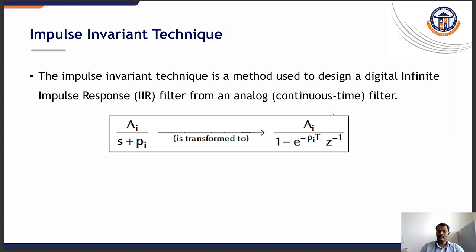While the bilinear transformation solves the aliasing problem, it also introduces a different issue known as frequency warping. The relation between the analog frequency and digital frequency is actually nonlinear, which means that frequencies in the analog domain do not map linearly into the digital domain. Lower frequencies are mapped almost linearly, but higher frequencies get compressed.